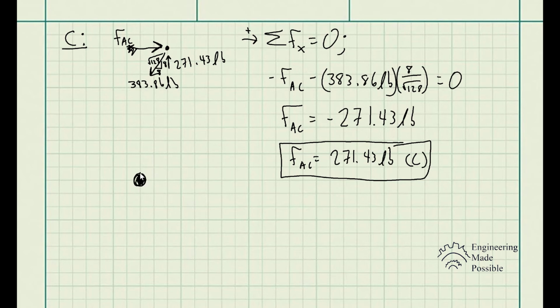But let's say we have two slender members here at this joint. Let's just say this one, we have this force F of AB, just arbitrarily choosing the letters, and this one is here, F of AC or whatever. Now, this member here essentially is being compressed. This is how you represent being compressed. The member is basically getting into the joint. This is how you would signify compression, whereas in tension, you'll be pulling away from the joint.